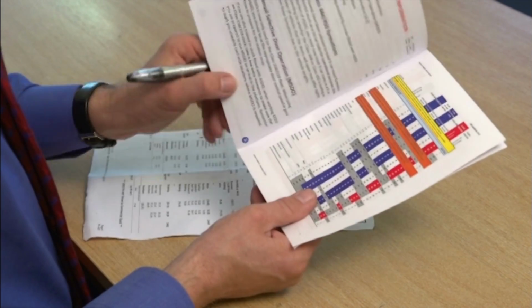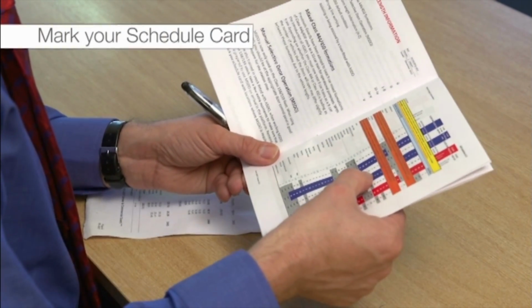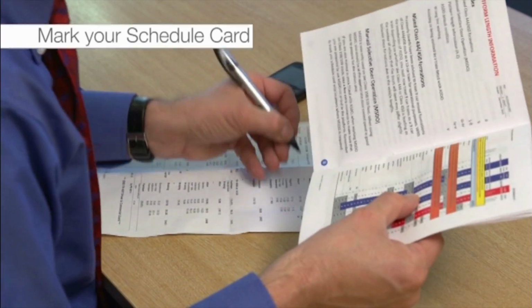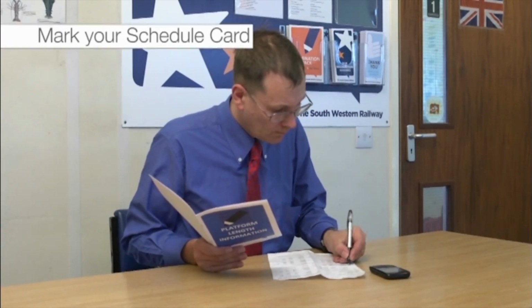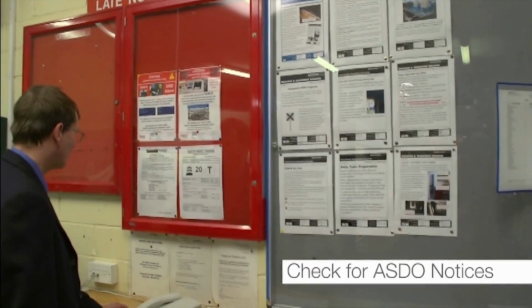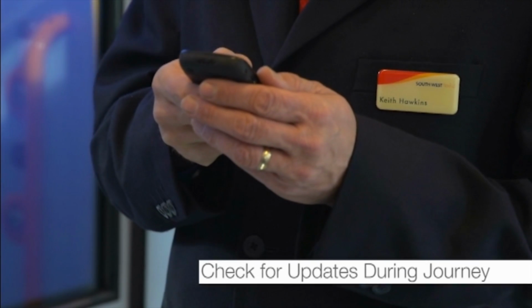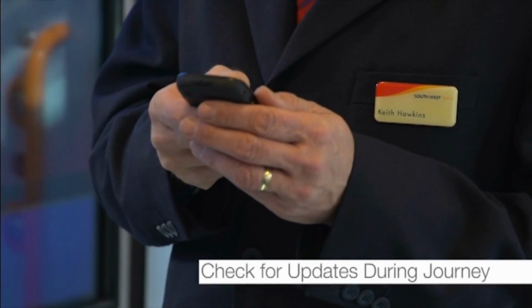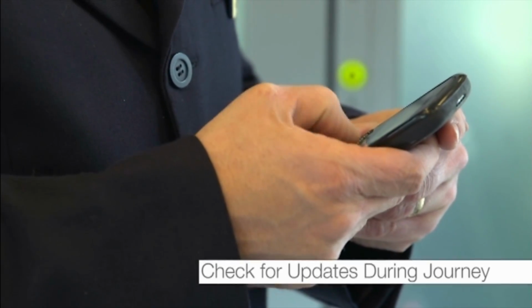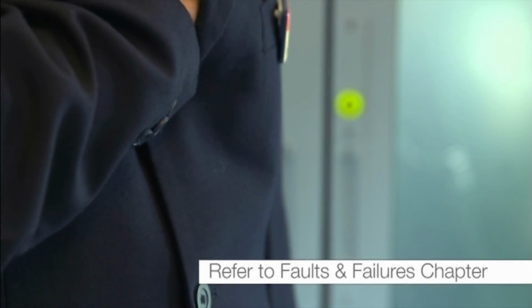Before each journey, you must use the Platform Length Handbook to mark on your schedule card the number of vehicles that should be released at stations with short platforms. Before leaving your booking on point, check for any notices concerning ASDO operation. During the journey, you should check your BlackBerry for any updates. You will be notified if there are any defective beacons. There's information on what you should do in this situation in the Faults and Failures chapter.